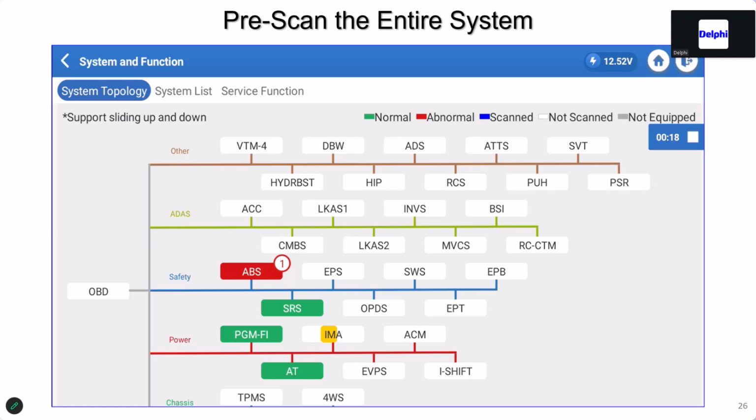Transmission issues. Again, scan the bus to make sure there's nothing hidden in another computer. In the future on these new systems, any computer that has emission-related data into it has to report directly to the PCM. Where this ABS here may report to the ABS computer that's a wheel speed sensor, but what they're not telling the PCM is that's where they get the vehicle speed from to be able to run the tests. So you got a blocking condition that's not reporting to the PCM, and you got to go find it. So please, get your later tools. They all have this now. Find a way to scan the bus and look at all the networks to make sure there's nothing hidden in the background. Okay?